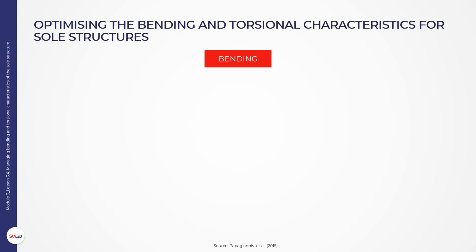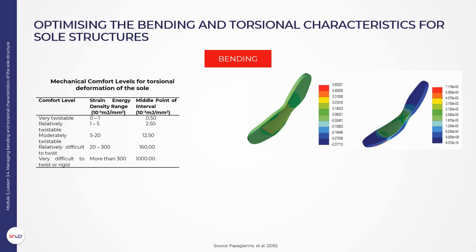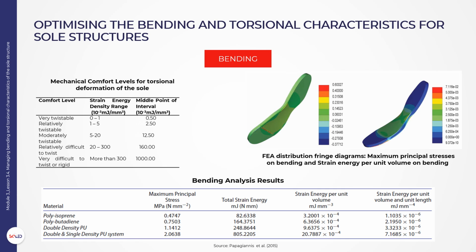The structure is fixed on its lower front side and the back part of the structure is bent upwards by a max angle 55 degrees. Calculated values for both maximum principal stress and strain energy are higher for increased Young's modulus of the sole material, indicating a realistic approach to assessing bending deformation characteristics of footwear components. This presentation of distribution for either stresses or energy quantities allows for problematic areas within the structure to be identified and sole design to be improved. According to the results of the analyses presented in the data from the Table 3, it is concluded that the soles are very flexible.